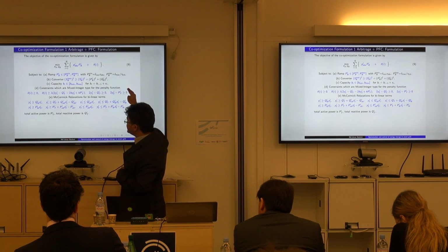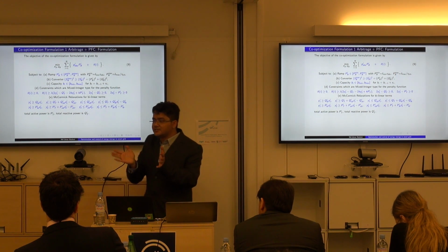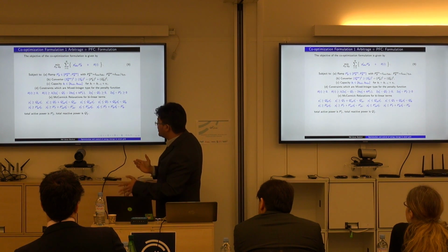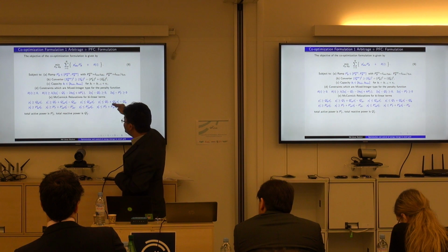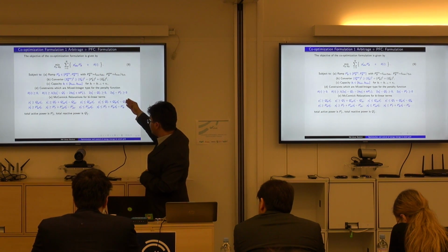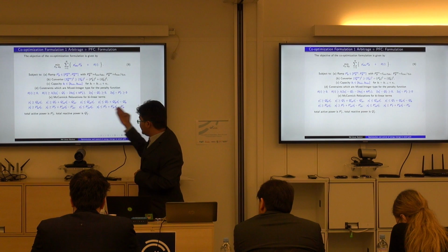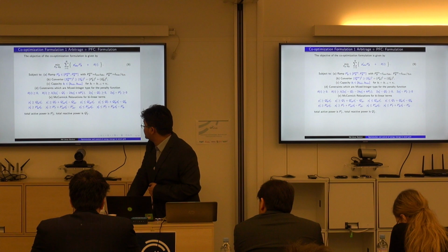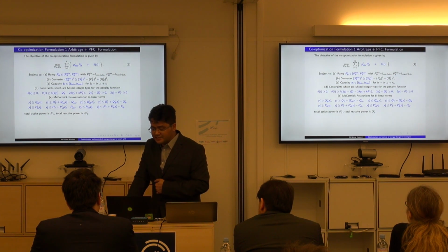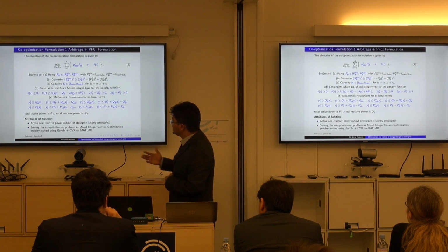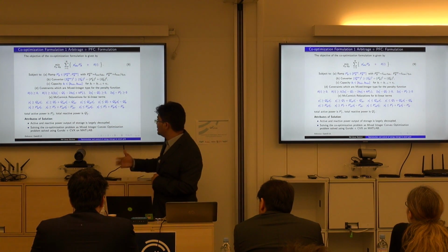Then this constraint D shows the piecewise penalty function, which penalizes whenever the power factor is more than or less than a certain value. And in order to simplify these bilinear terms, which we have denoted in the previous constraint, we have these four constraints for each of these bilinear terms. So it turns out that this problem can be solved as a mixed integer convex optimization problem using traditional solvers such as CVX and Gurobi along with it.